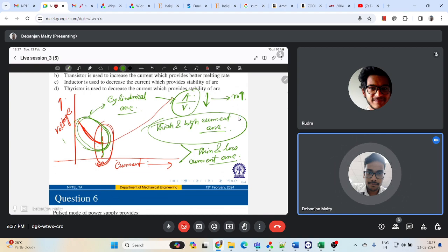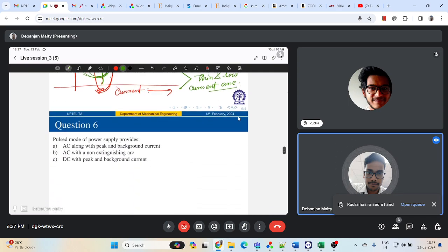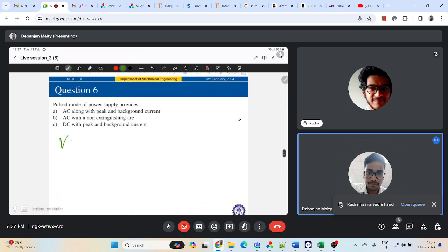Now, as a first approximation, we can assume the conductivity of the arc column to be independent of the arc length, and the voltage drop will be linear. So we can write the voltage drop across the entire arc gap.